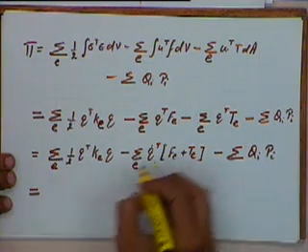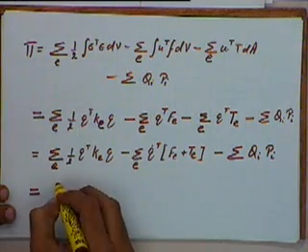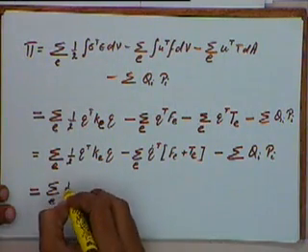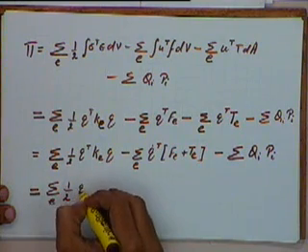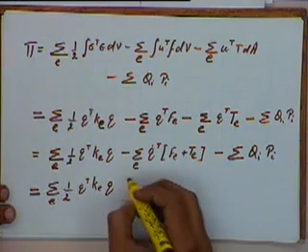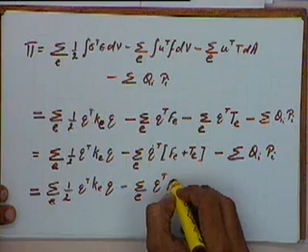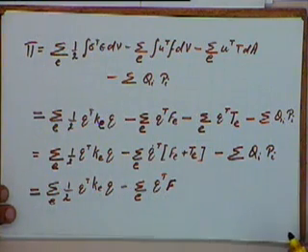So this again I'll write as summation over all the elements half of Q transpose KeQ minus summation over all the elements of Q transpose multiplied by the element force vectors.